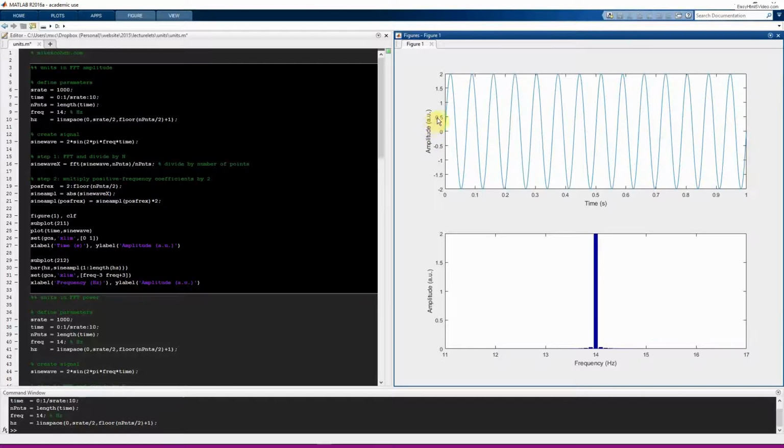So you see here, in the time domain, the signal has an amplitude of 2, and here in the frequency domain, the signal has an amplitude of 2. Doing any other manipulation here, you'll see that this will be incorrect. So this will not match this. And by the way, in case you're wondering why the amplitude is 2, maybe you're thinking it should be 4 because it goes from -2 up to +2, then you have to go back and review some of the old lecturelets on extracting time frequency information out of complex Fourier coefficients.